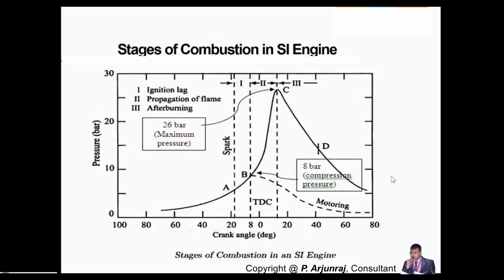Under motoring condition, what will be the effect? When you don't have the fuel and the moving components like piston, crankshaft and camshaft are all in moving condition, the friction that develops in this particular motoring condition is likely going to be the worst one. That is the reason they sometimes go with the motoring condition for friction power and friction mean effective pressure.